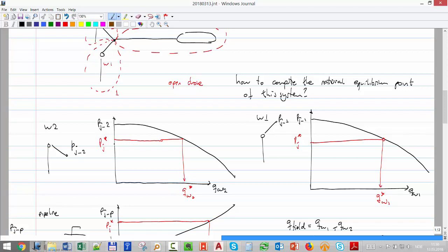But remember, like in the single well case, we had two ways to calculate. One was to find exactly the equilibrium point, and the other option was to remove any object that allows me to control the system, perform the computations upstream and downstream, and then see what will be the delta P, if I had a choke. You remember that, right? We did it on the single well.